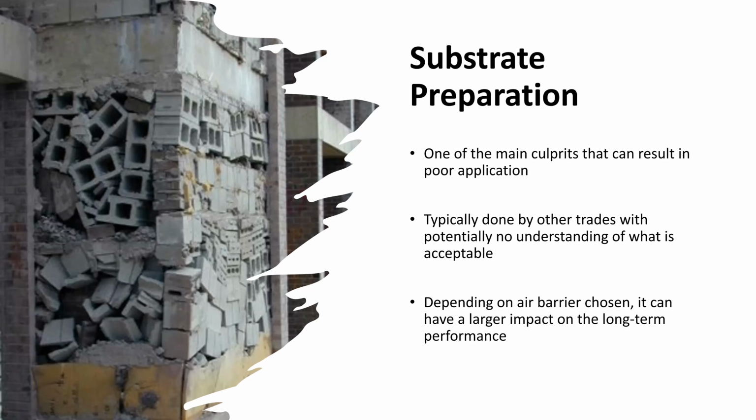So from a design standpoint, right, we always want the specifications to refer to the other related sections. And if you look at an air barrier specification and the related sections, it's extremely long, right? There's so many different things within a wall assembly that can actually impact the air barrier. It's almost hard to even manage sometimes. There's just so many things that touch it, from whoever's doing the exterior cladding to the structure to insulation to through wall flashing to windows. You've got all these trades that are working with the air barrier to make the building airtight.